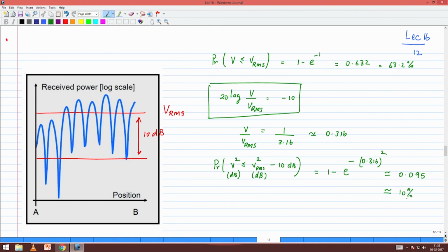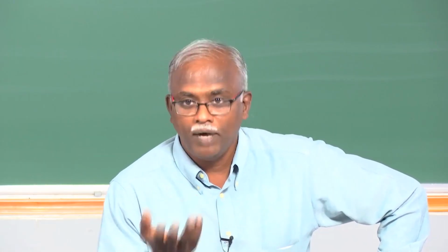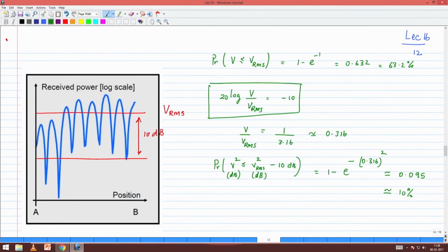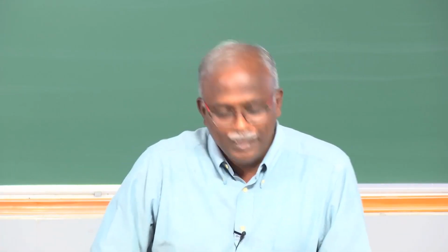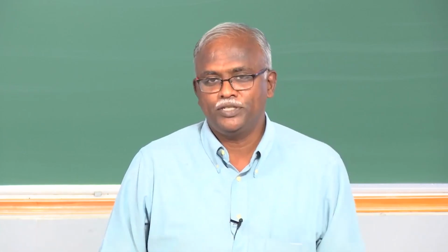Okay? Good. We have accomplished something very significant in today's lecture in understanding what is the price that we have to pay to build a system that is robust in Rayleigh fading. What is the secret? Margin. Now this one says with 10 dB, I am likely to have 10% outage. No problem. We are going to live with that, but now the engineering intuition starts to kick in.